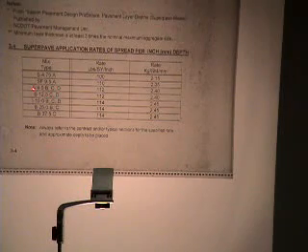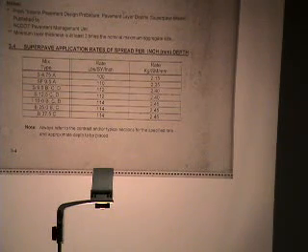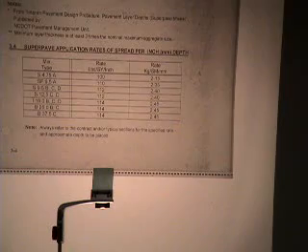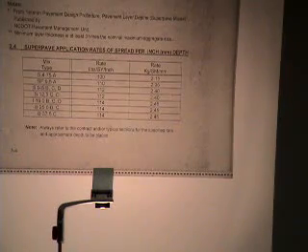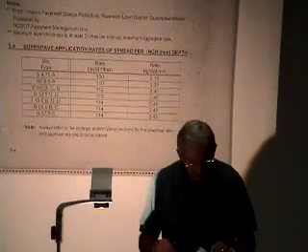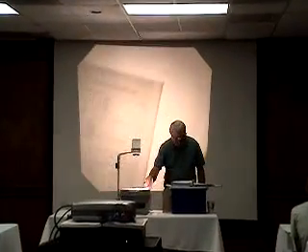And for example, here, it varies. The coarser the mix is, the higher the unit weight would be, because it has more aggregate on a percentage basis and less asphalt than the surface. So that's why it's different. But these again are the numbers that are actually used to compute quantities in contract. Any questions? Another table you may be interested in is one over on page 3-6.